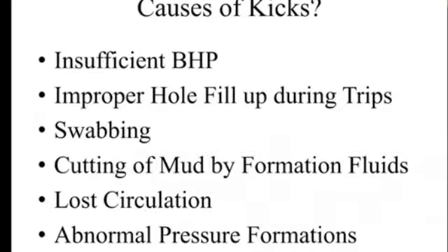Now we know about the importance of well control, what happens if we fail to manage a kick, and also we know about bottom pressure, the dynamic and static bottom pressure. We know about the mud window, fracture propagation pressure curve, pore pressure, the safe zone. The next step is why a kick happens.